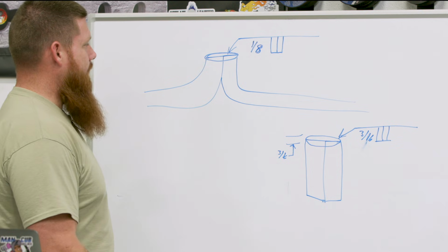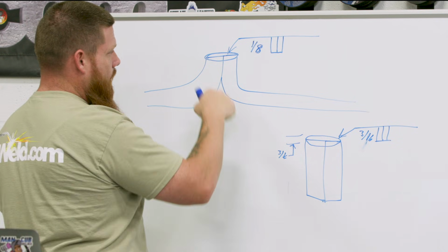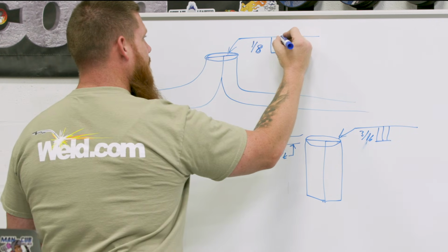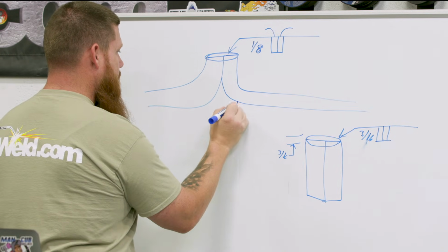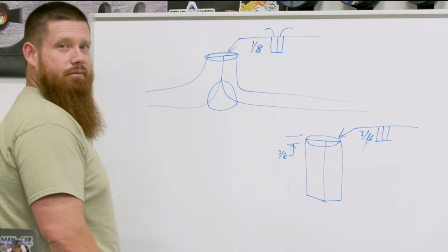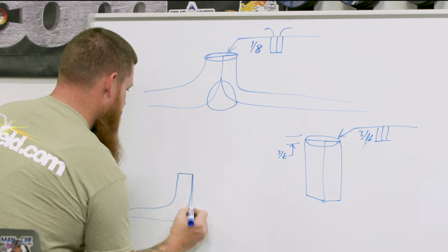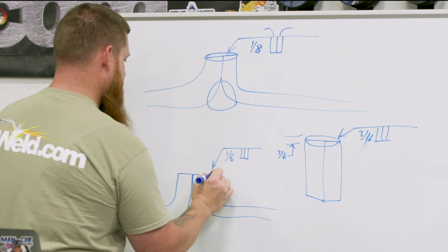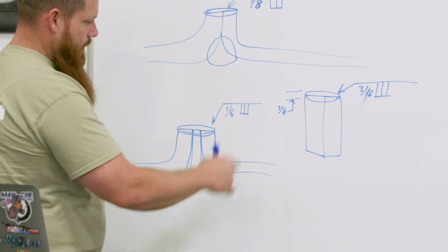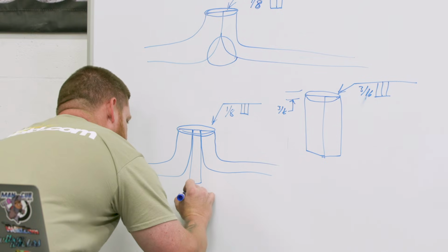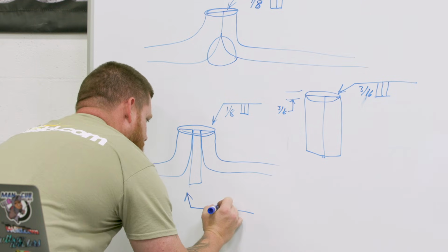Okay, now let's say we want to weld here. So what are we going to do? On the arrow side, we have our edge weld, and let's say we have a flare V in here as well. So we're just going to go ahead and fill that flared V in. All right, so another instance, we can combine 3 pieces of material together. Okay, that tells me I have to put a 1/8 inch weld in here. I'm going to join all 3 of these pieces of material together. So we have our edge weld up here, but then I want to put another weld down here. I could say put that flared V in there.